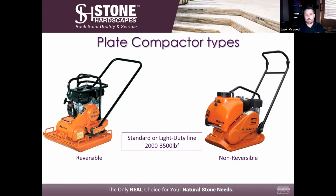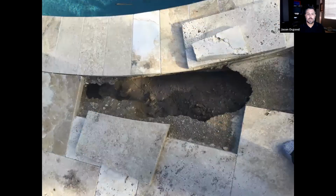Now, there's a reason, again, why we harp on making sure your base is done well. You don't install your base properly if you don't make sure that it's compacted well, if you don't make sure that it's pitched the way it needs to pitch to run the waterway, you're going to have issues. One of the issues that you'll come up with is the deck itself, the base will collapse and the pavers will sink over time. It's unsightly. It's difficult to fix. If you do it right the first time, you don't have these issues.